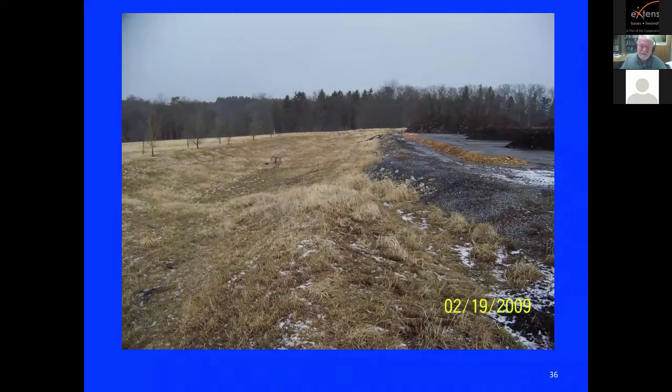This is a different type, but still is an infiltration basin. If you look closely in the middle of that basin, there's a drain area, and that's a pop-up drain for when there gets to be too much water in that basin, and it draws it underground to another basin, a secondary basin. That riser is in case of a lot of runoff. In this case, this is up at Penn State, where they have their food waste and yard trim compost site. This one almost never fills up with water. The secondary basin has never been filled. It has had water in it, but it's never been filled.